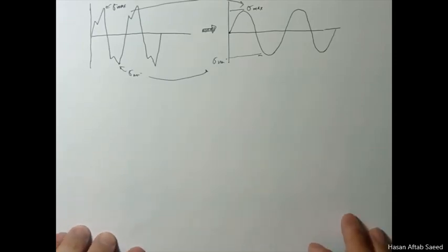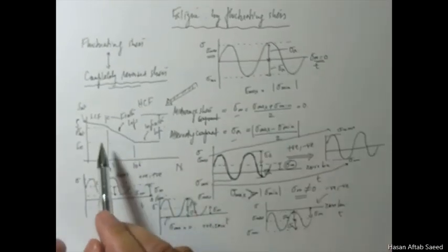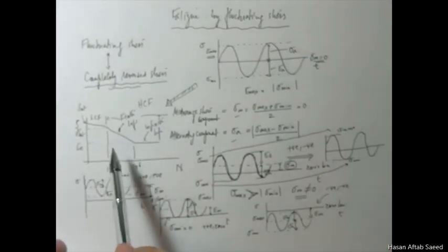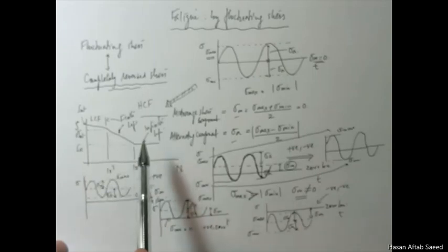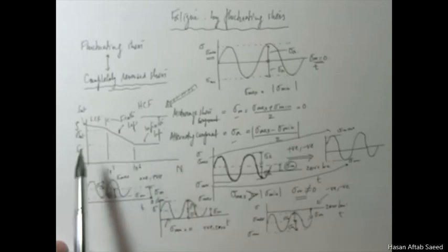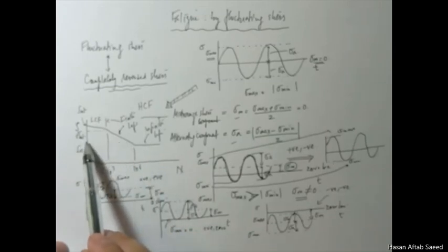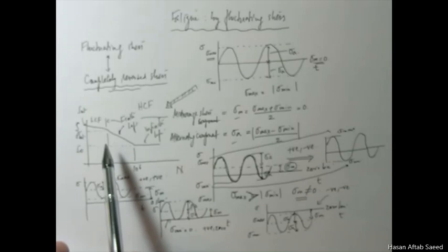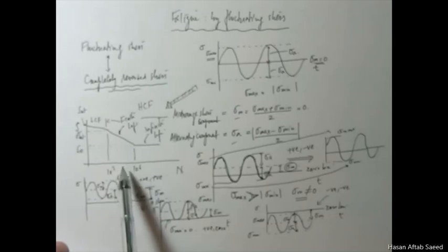The problem that we are facing here is that we have all the analysis tools with us available when we talk about the fully reversed load case. So here, if you want to design for a certain life, you can just read the stress here. If you have a certain stress in mind that you want to apply, then you can read the life.